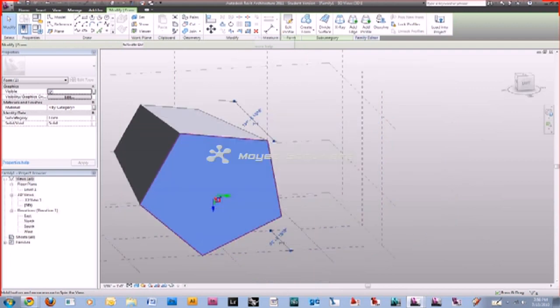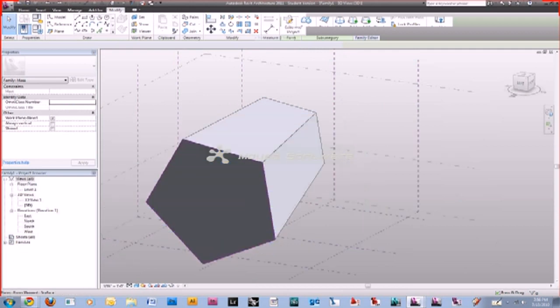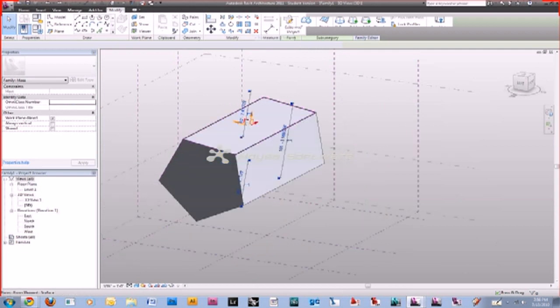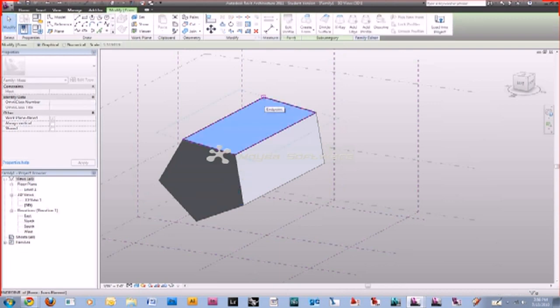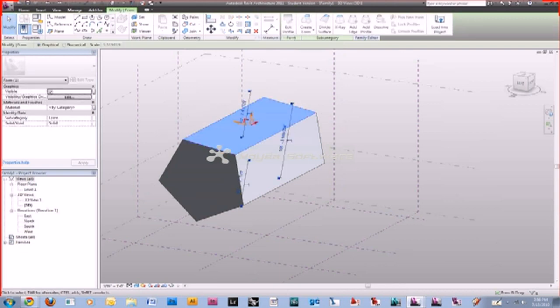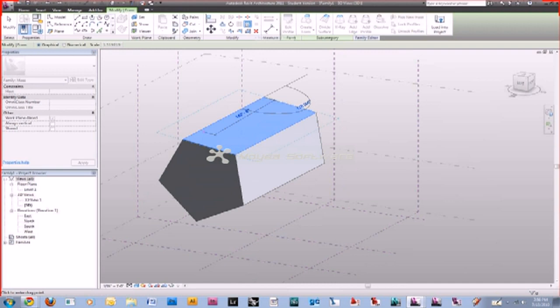But if you want inches, this is the most confusing one: you don't have to put a quotation symbol. I'm getting all my words mixed up. You don't have to do a quotation after inches. You can just do feet. So if you wanted to do 1 foot 6, you just do 1 space 6, and it knows that 1 is going to be a foot, and then 6 inches. So it automatically knows that, and that saves a lot of time when you're typing in feet hundreds of times a day.